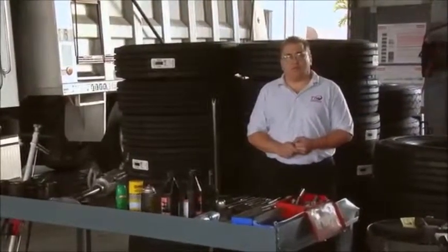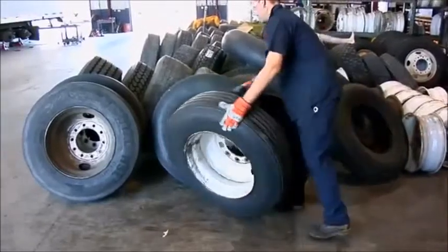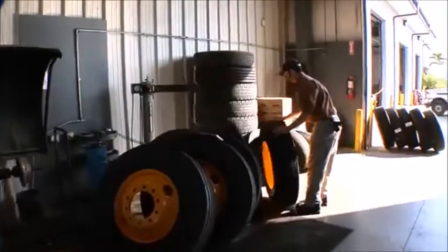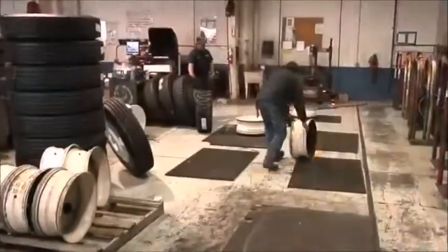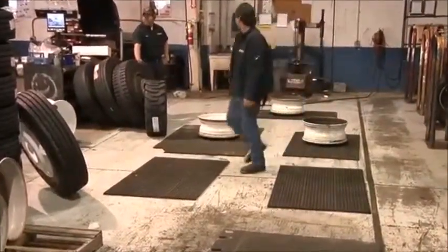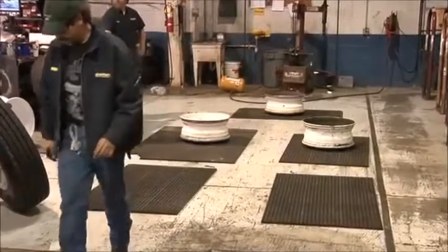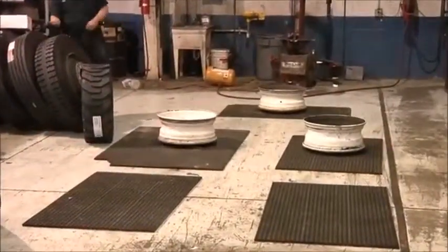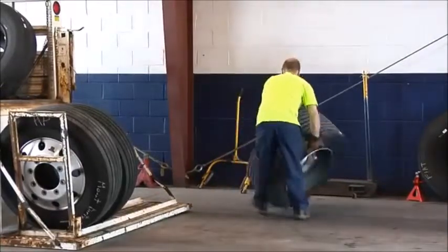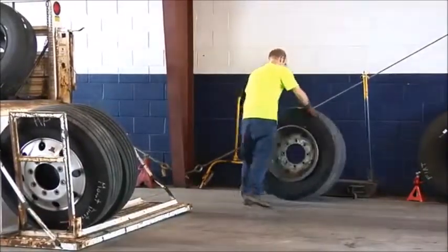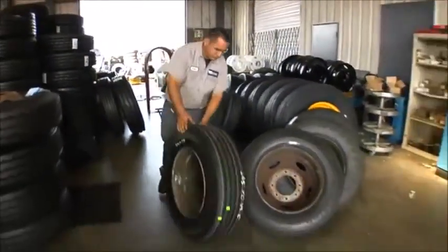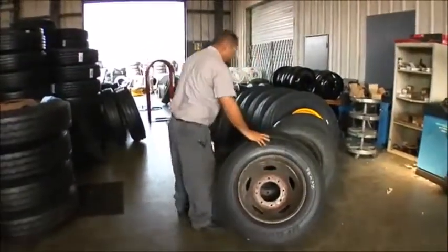When tires are temporarily being stored in the work area, make sure they are not in the traffic pattern and cannot fall on someone if they are bumped or moved. Wheels and rims should never be stored in an upright position because they can easily roll into the path of anyone working in the shop. Tire and wheel assemblies should never be stored or leaned against a post with a disc facing outwards. If the assembly falls over and the disc is facing out, it becomes a hazard for anyone in front of the assembly. However, if the disc is facing in, the assembly will fall straight to the ground without endangering anyone in the immediate area.